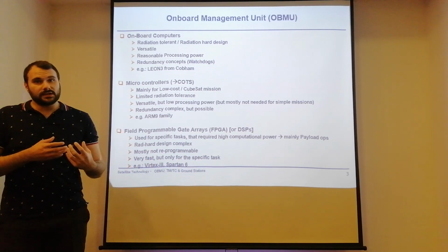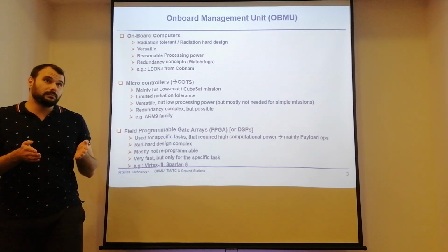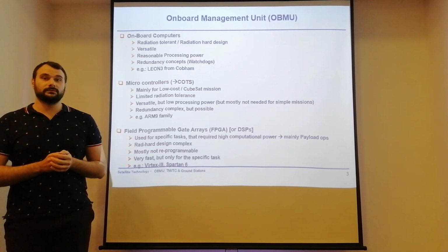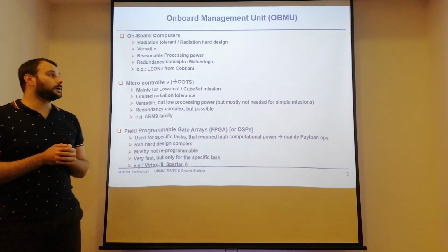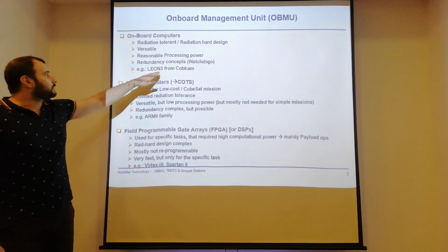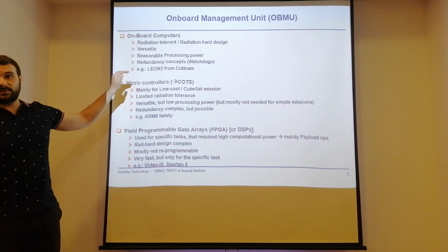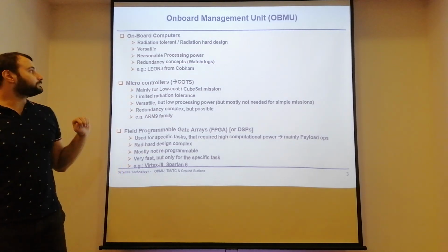Once those signals are missing, something is going on, something is faulty, possibly within the onboard computer, and one way to resolve this issue would be a reboot. This is a watchdog. An example would be a Leon 3 from Cobham, which is a completely space-qualified onboard computer for satellites.